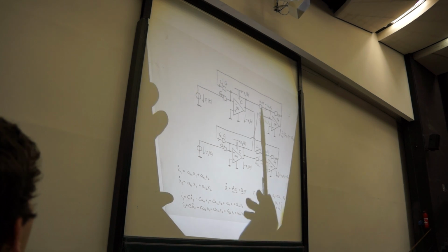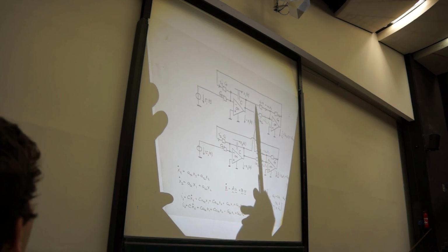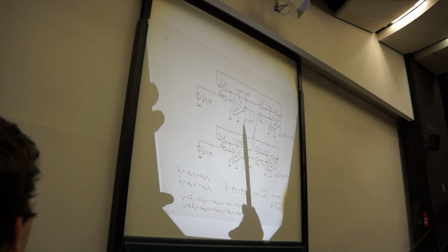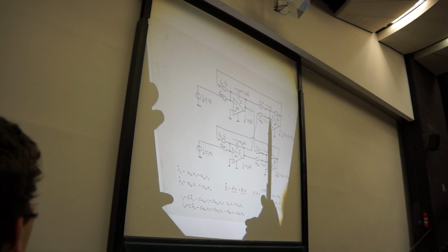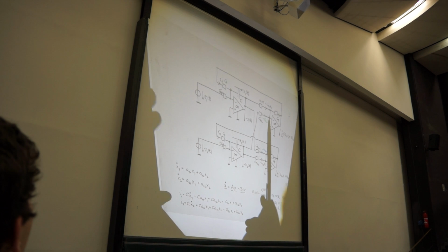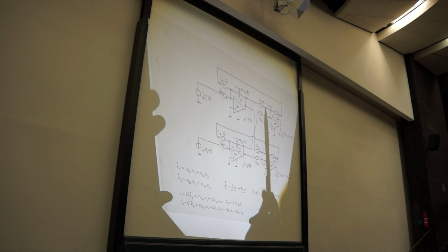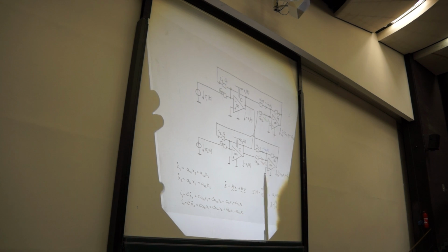By simply choosing a conductance with value capital G11 here, a current flows through that conductance, which is determined by minus G11 times X1, because we have minus X1 here as voltage, and at this terminal we have virtual ground. That's because of the nullator here. Then this current has to go into that conductance. There is no other way because of the nullator.